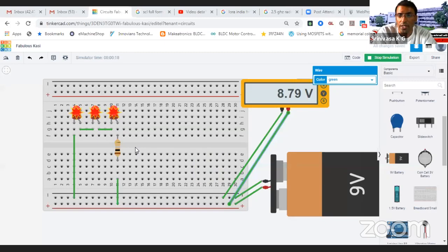So it's not that we have to not put direct heat and trial. We have to calculate with formula. So it is not universal that you have to use 1 kilo ohm, because when you are going to build any product, then precisely you have to calculate. Yes, someone has given answer 150, so 150 ohm LED is working fine.